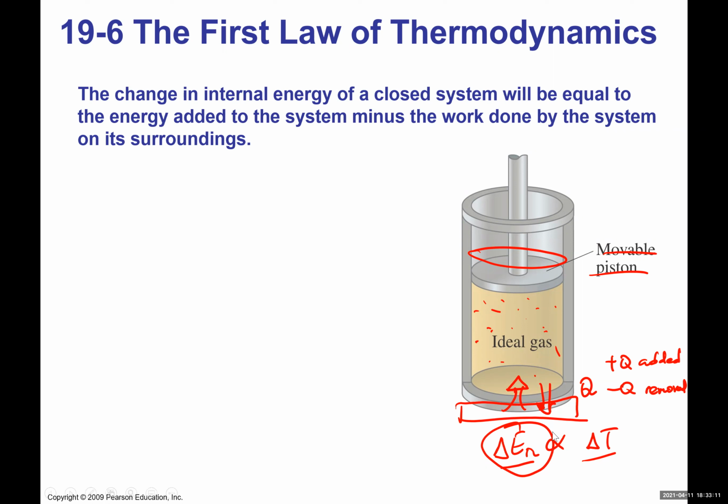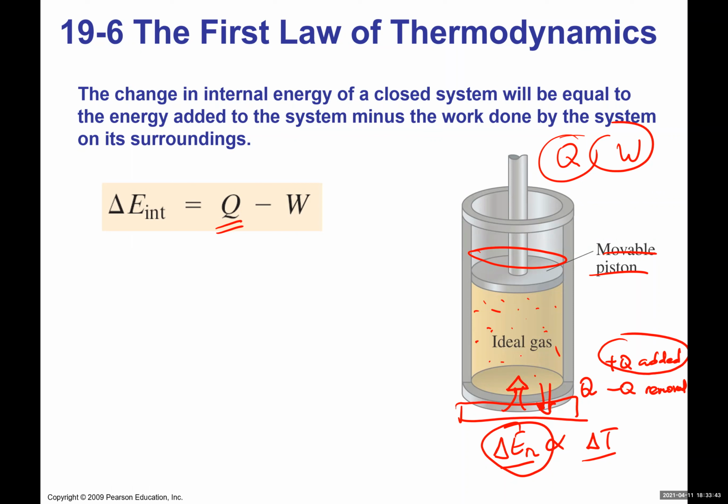So then what we have here is internal energy. You can see, right? So basically we have Q, and we have work done, and these are two ways of adding energy or removing energy. So let's say two ways we can change the energy of the system. Those two combined together will give us this equation for the internal energy, where the change in internal energy is equal to the amount of heat added or removed from the system. As I said, it can be plus if it's added or minus if it's removed, then minus work done by the system.